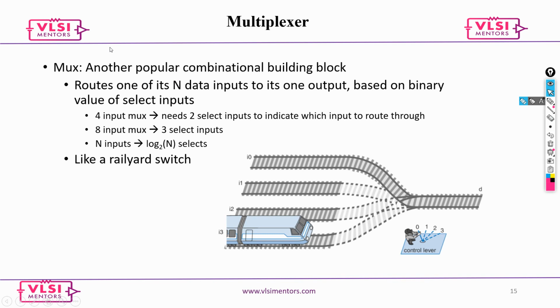So if you look at it, a mux is basically a device, or you can say a circuit, which has many inputs and only one can be chosen to go as output. The mux's work is to choose one of the inputs based on the control line.